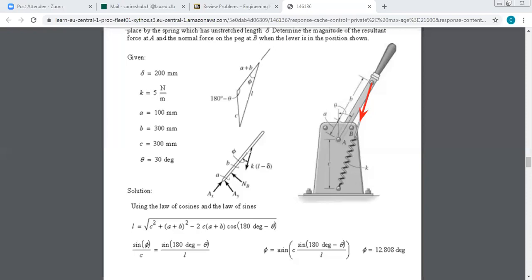You know that for a spring, the developed force is equal to what? K delta L. Yes, exactly. So force of the spring is equal to K times delta L. So if I find delta L, then I will reduce my system to 3 unknowns, and I can write 3 equations with 3 unknowns. So now before writing the equilibrium equation, I will try to find the tension force. This is why I should find delta L.